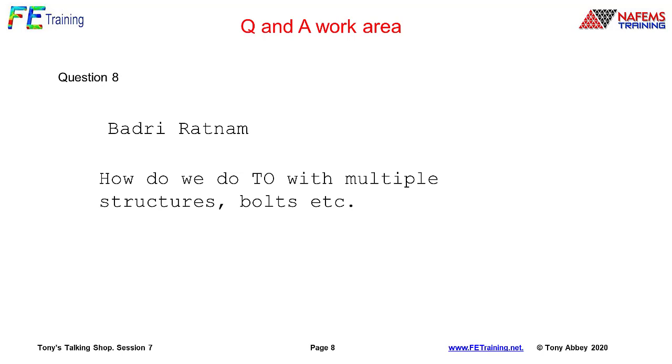That then gets interesting. It's a very, very big question. Sometimes, if we take a wing, for example, and say let's do a topology optimization for a wing, and the whole thing is going to be driven from the word go with topology optimization, that's almost doomed to failure because we have our standard fittings, parts, other things we want to do. So there's more of a cascading type approach. We might get an initial optimization using other methods to get the overall wing layout and so on. Maybe sizing optimization as the final approach is my experience.